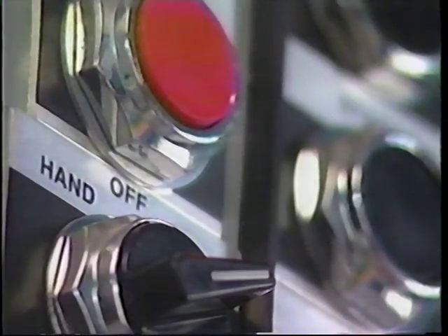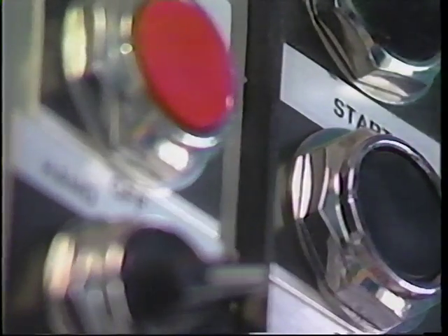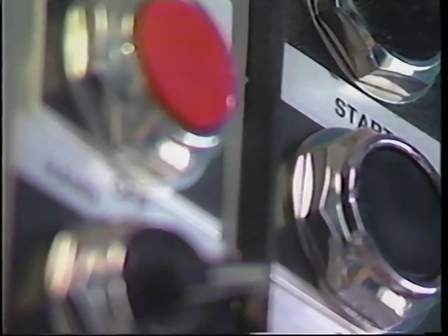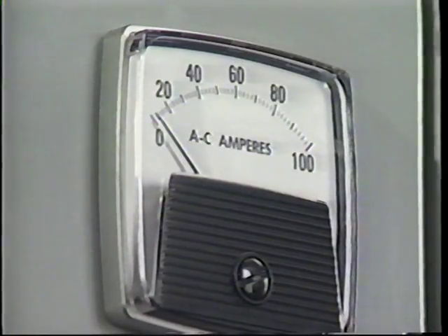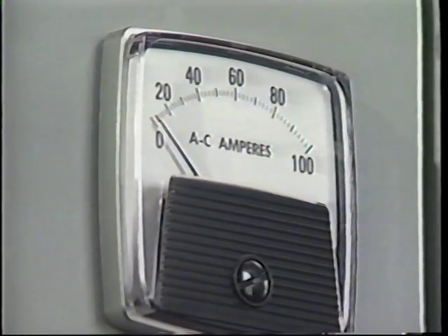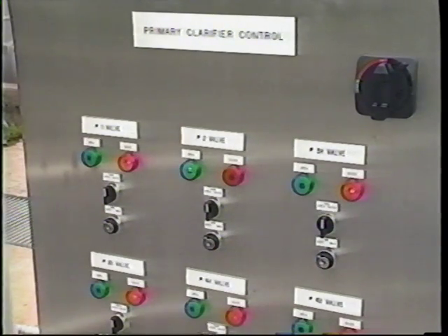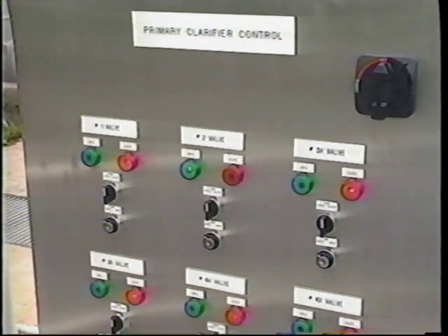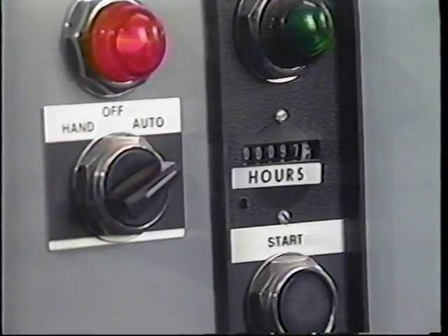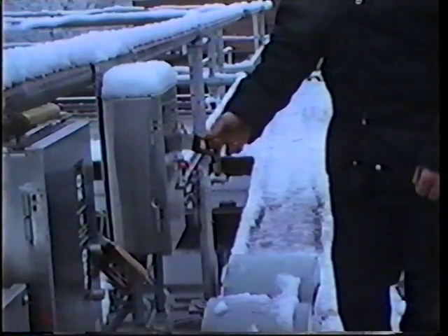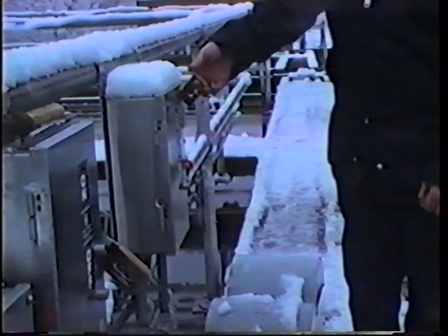Restarting the mechanism with a heavier shear pin is not the answer and could cause serious damage to the collection mechanism. If the motor fails to restart, it could indicate a variety of problems, such as an open disconnect switch, a motor starter that may need resetting, an electrical circuit breaker in the off position, or that the motor itself is defective. In any event, the problem needs to be diagnosed and corrected.